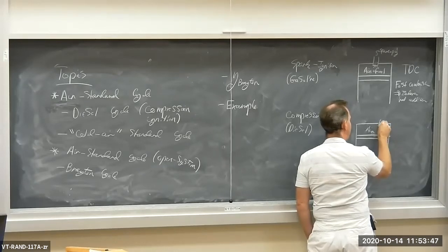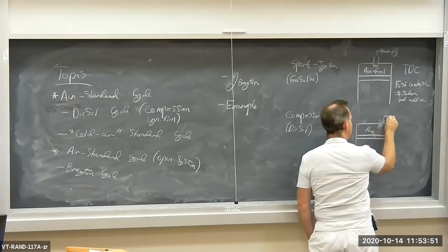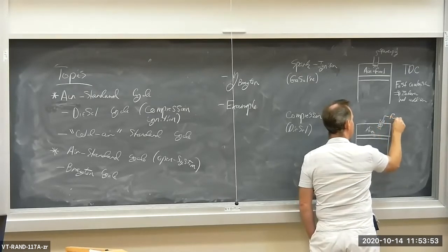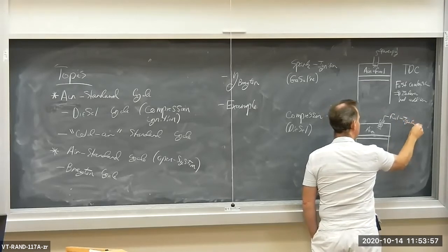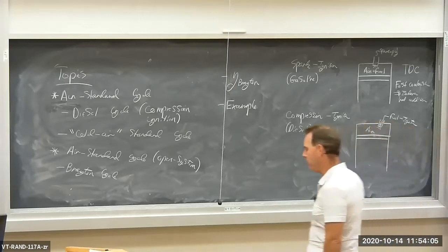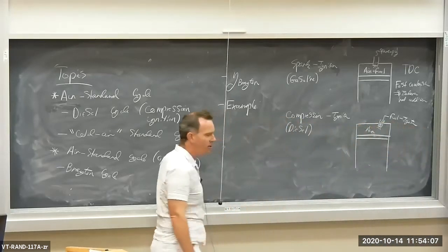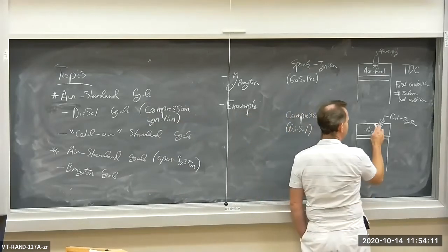So there's a little passageway here, and we are squirting fuel. Fuel injection. Okay, so we're squirting fuel into this highly compressed, high pressure, high temperature air near top dead center. And the fuel burns as it is injected.